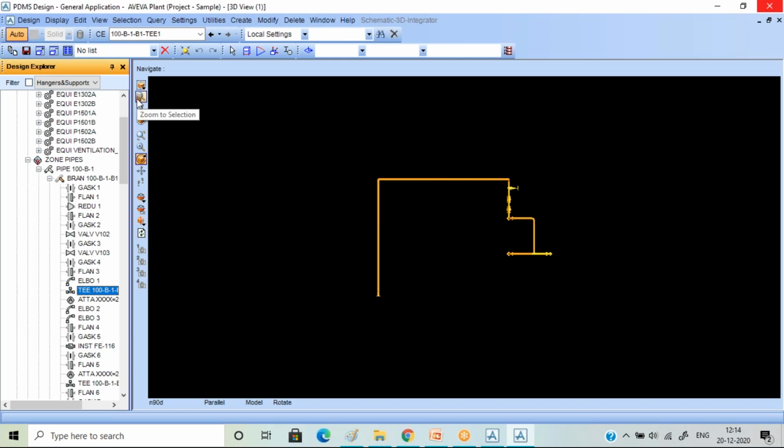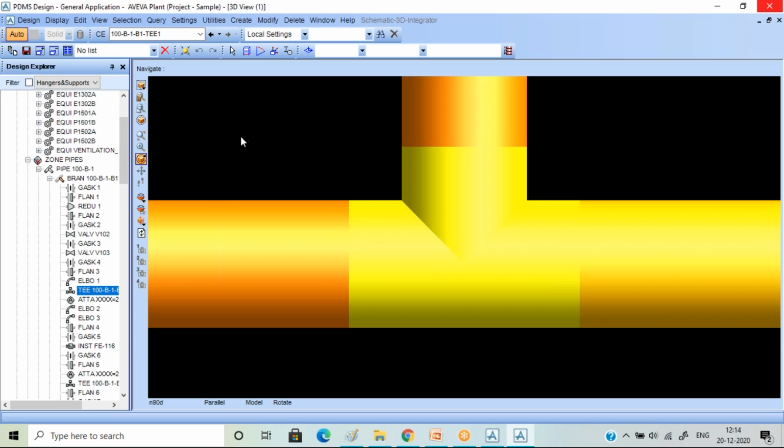You must have seen, whenever we're modeling a temperature element, if it's a smaller size line, say a line of 2 inch, we give certain reducers. Now why do we give those reducers? Why do we want to increase the size of the line before installing this temperature element? Obviously because there are certain requirements for a temperature element. The probe has to go up to a certain distance in order to have an exact reading, right? Now how is that probe? Is it a tapered section? Why do we use a tapered section? Why not a straight section for that probe? Now that particular small niggle in your piping will be explained again.